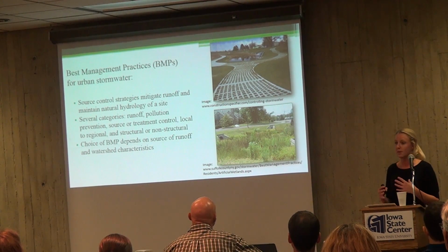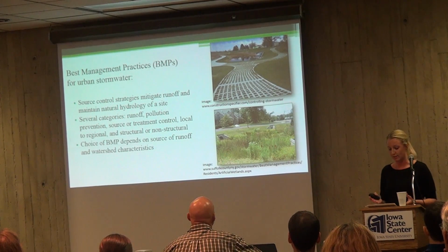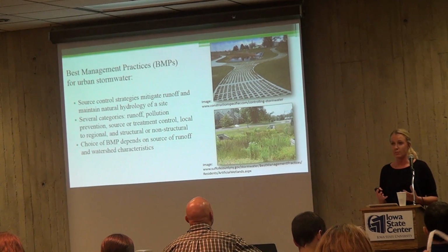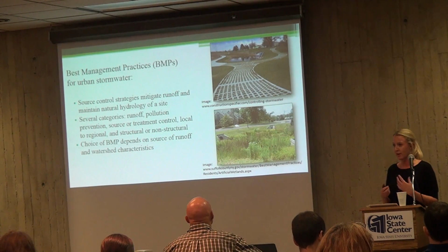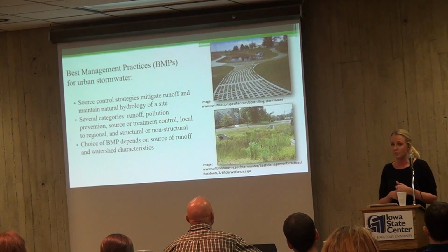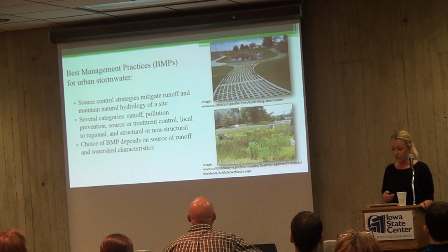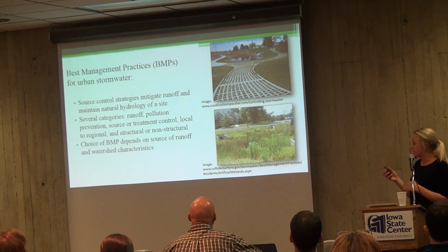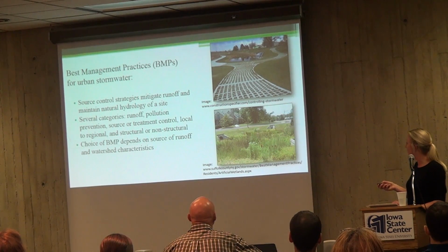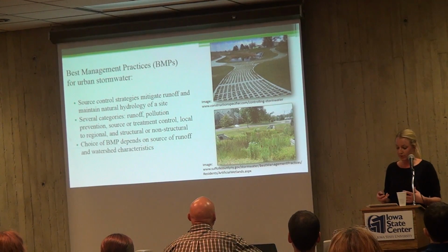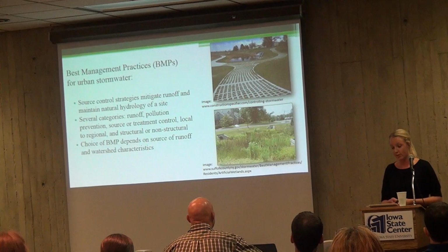In our study, we focus on BMPs that are categorized as non-structural practices, which are designed to minimize site disturbance and create a disconnection or reduction of impermeable surfaces. Examples of non-structural BMPs include wetlands, vegetated filter strips, soil compost application, or vegetated swales. Here are two examples of non-structural BMPs, one that utilizes permeable pavement and a retention facility, and one that uses more of a wetland approach. In our study, we chose to assess three best management practices: bioretention cells, restored prairie areas, and riparian buffers.